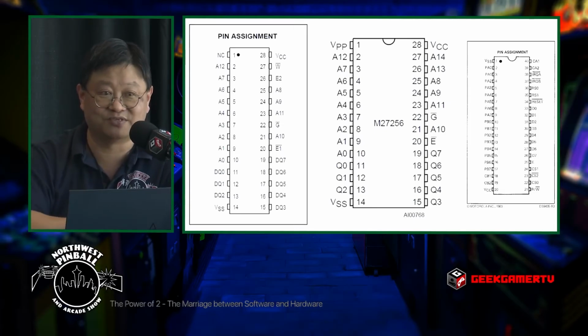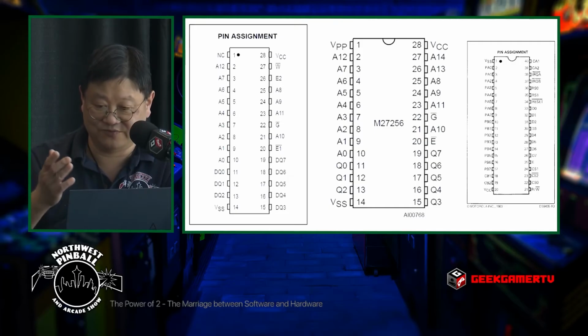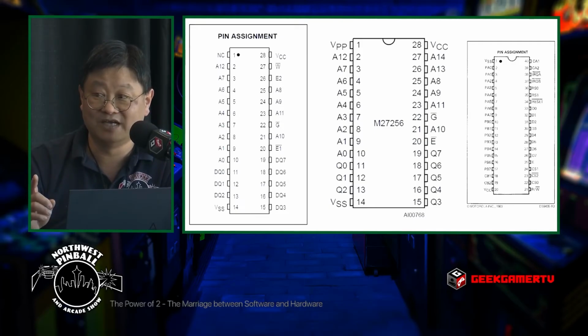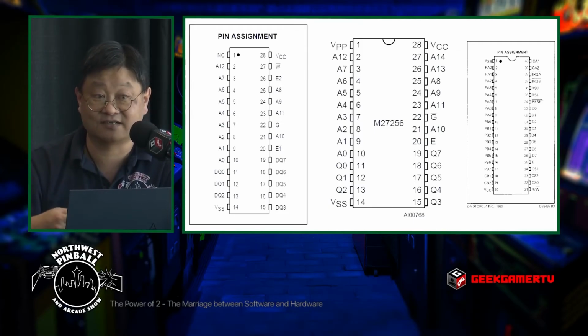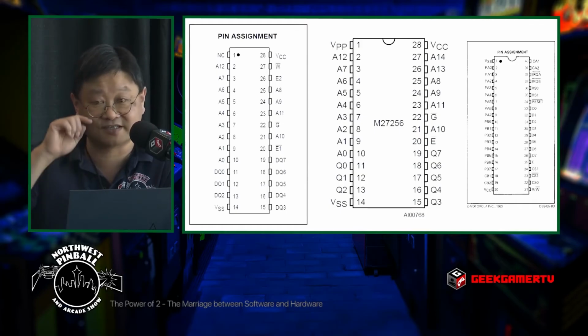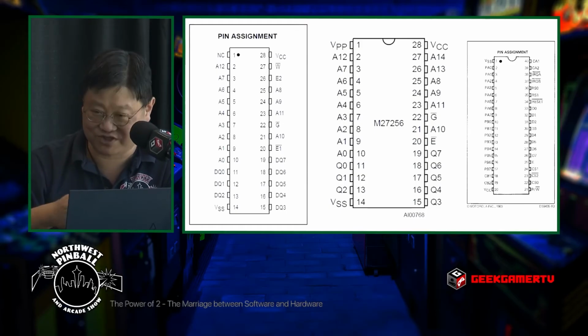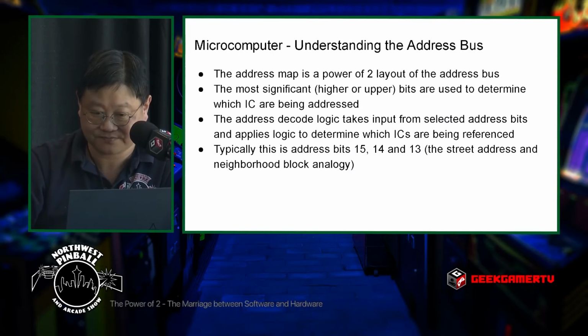The chip's got it built into it. You just need to supply the relevant signals. If you only need one signal, then you can tie those pins that you don't need to high or low to satisfy the chip select condition. That's the easy way around it. That's why oftentimes you'll find chips have multiple chip enables or chip select signals. Anything you don't want, just tie it to what it should be. It's either always high or always low.